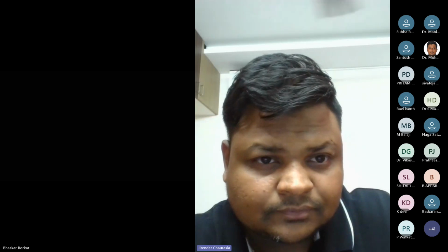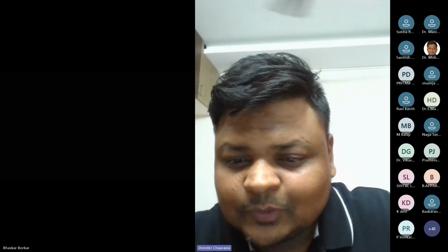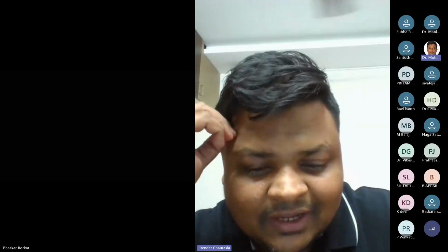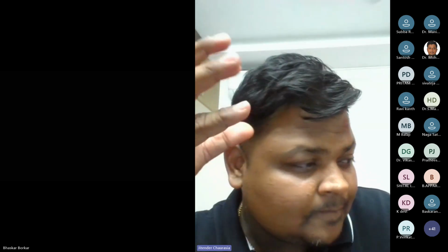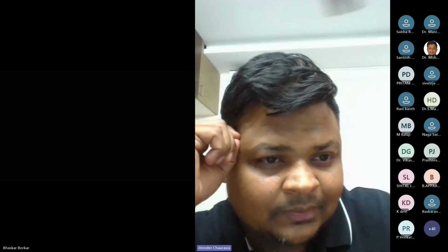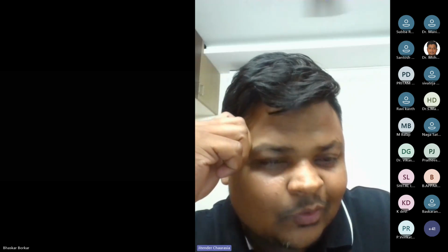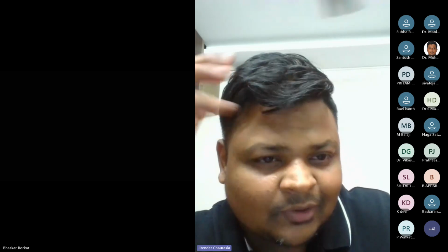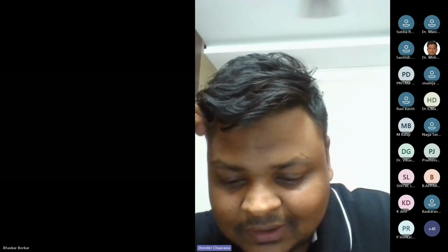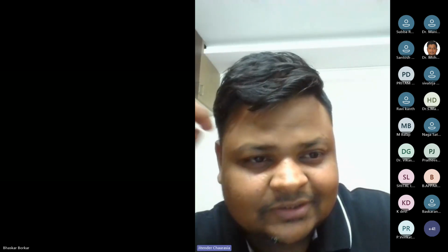Sir, I have one question for you. Today I got one challenge. There is one toilet seat, a plastic part, that I have to reverse engineer. What is the best way to find out what material it is? It's a plastic. I am not a plastic guy, I am a metal guy. FTIR is good, Mr. Manish.